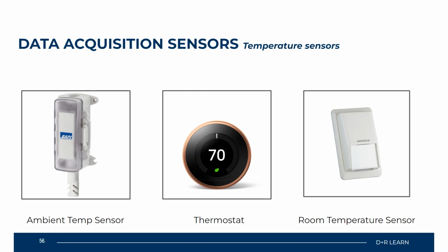So what they are doing is these components, the room temperature sensors, are sensing the temperature in the space, and it is relaying that information back to the mainframe or the main system for the building automation control, or building automation system. The reason this is important is because we have to understand what the temperatures are within a space in order to provide it with what it needs.